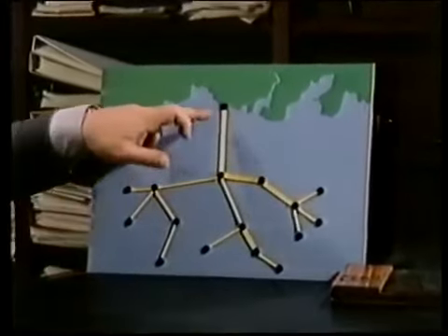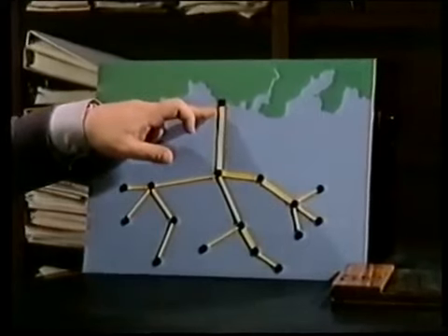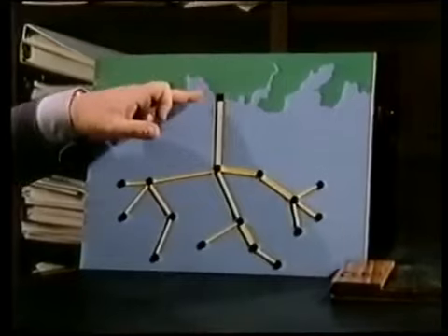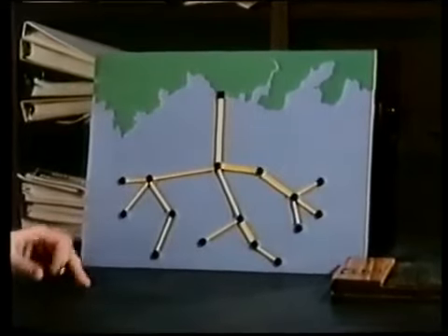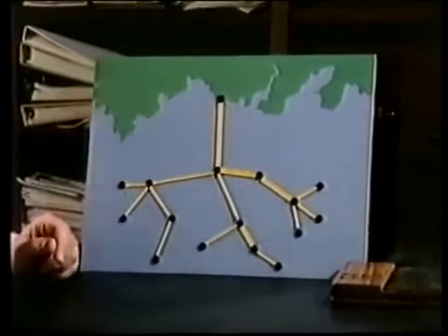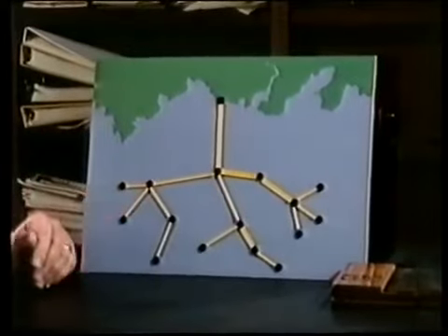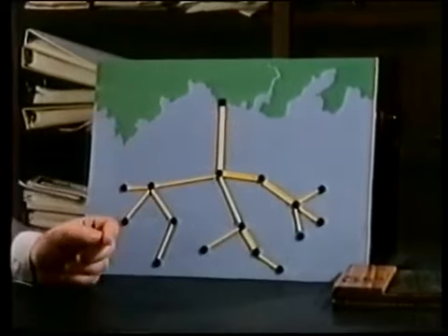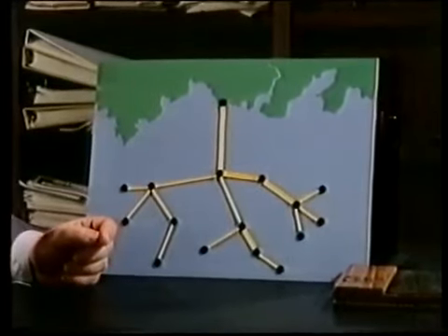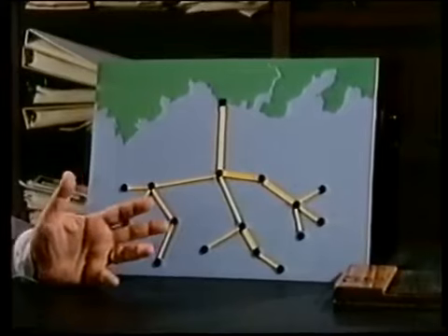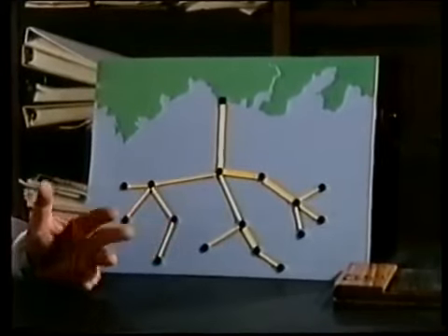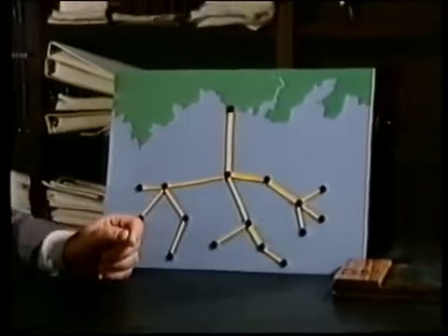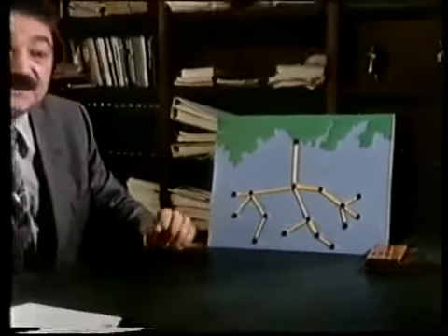For example, if I delivered the gas with a very low pressure, then I would have to spend a very large amount of money at the onshore point to recompress the gas for transshipment. If I delivered the gas at a very high pressure, because of the fluid dynamic equations governing gas flow, I would have to spend a very large amount of money for the actual pipeline sizes themselves. So consequently, my design problem is a compromise of picking the right size diameters to meet the pressure constraints with a minimum cost. If I could solve that problem, I have a second problem.